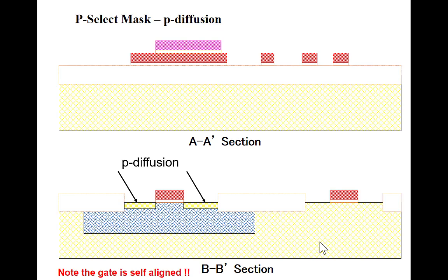Okay? So a process that has that characteristic is called self-aligned. The drain and source are aligned relative to the gate. The alternative could have been to have a mask opening that was this wide, and then we exactly put the source where we want it and exactly put the drain where we want it. Then if you didn't have alignment of the drain and the source, you might have a gap on this side or a gap on this side. Does that make sense? So we could have put this process together and not have it self-aligned, but our yield would probably be bad.